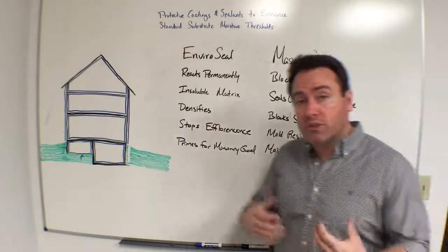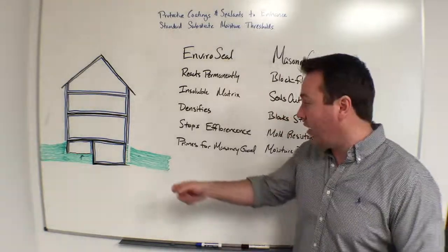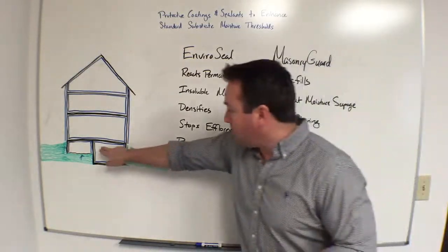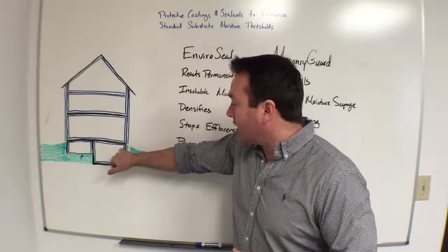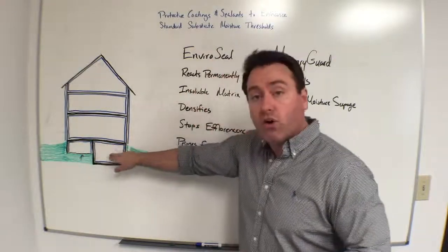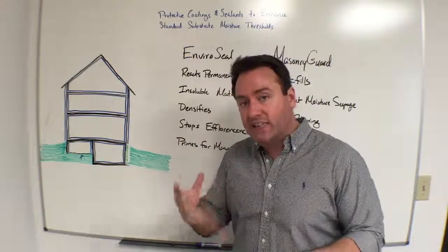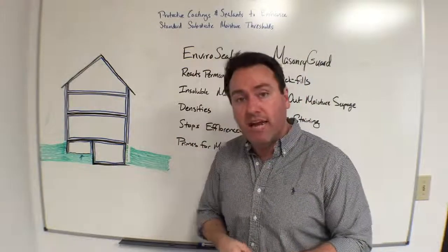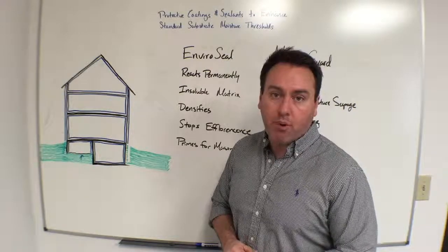Add to that the moisture resistance, again from ASTM D5590 testing standards, and you're talking about a product that is proven mold resistant. And speaking of condensation and things of that nature, Masonry Guard is great so that if moisture does begin to accumulate in these areas, much like we talked about in the crawl space, humidity builds up over time, even if it's condensating on the interior of that, it's going to prevent that moisture from moving back into the surface that it is protecting and give you a high-performing, moisture and mold resistant product for the structure.